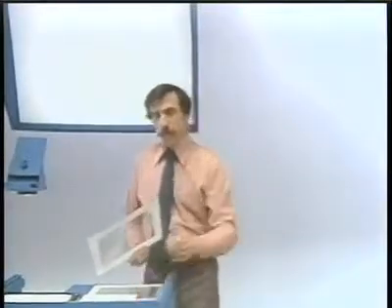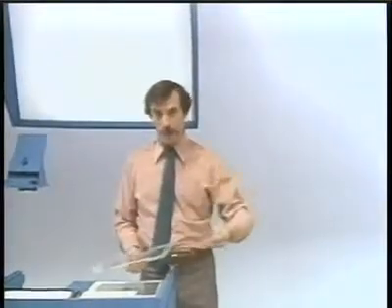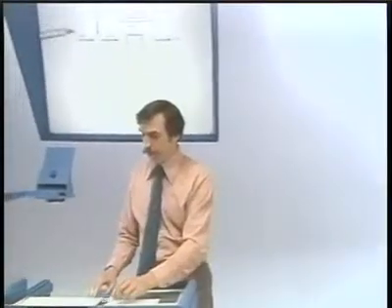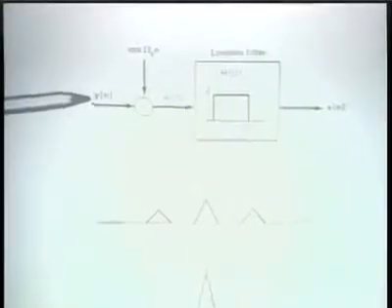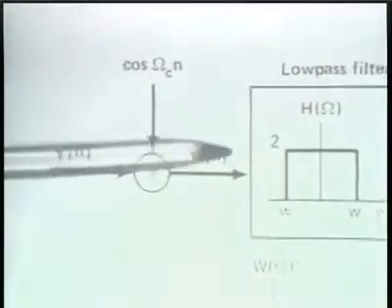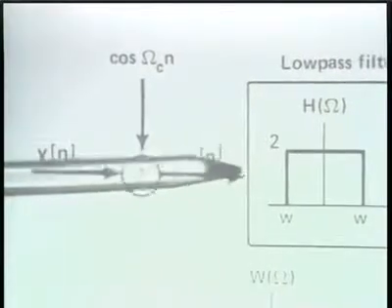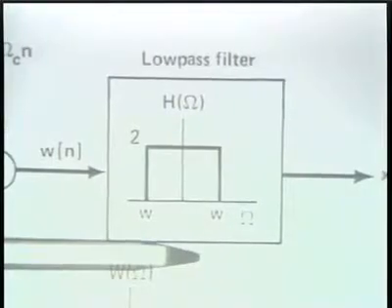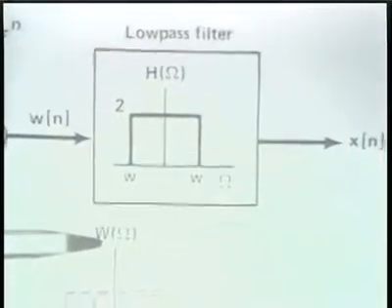So once again, things work out basically the same way as they had in continuous time. We have sinusoidal modulation, which consists of using a sinusoidal carrier, and we have the demodulator, which consists of taking the modulated signal, multiplying by the carrier, and then processing that with a low-pass filter to extract the portion of the spectrum which is around zero frequency, as I indicate in the spectra below.